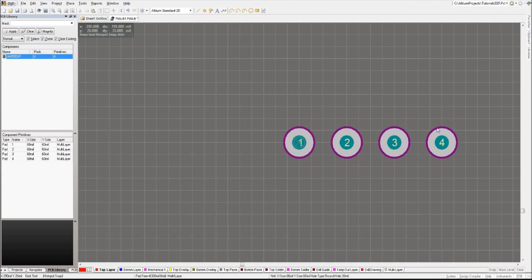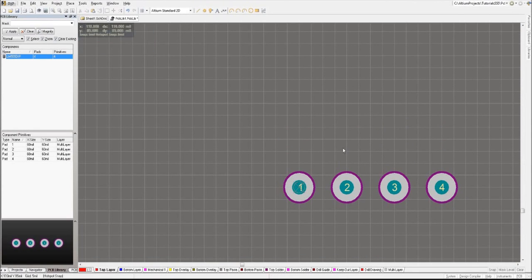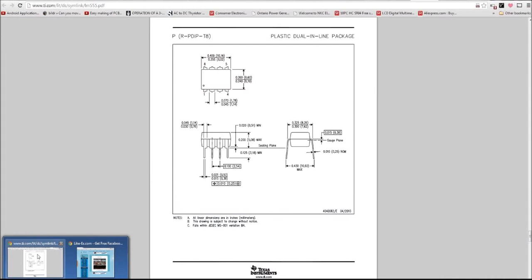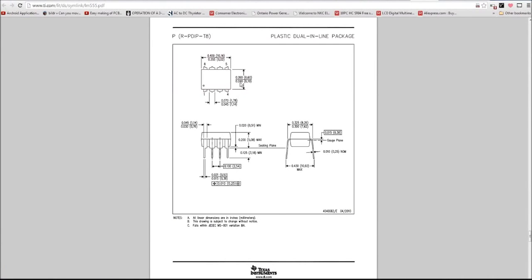So you have your first 4 pins ready for your IC, and now we're going to see what the spacing is between these 4 and the top 4. As you can see, it's 0.24 to 0.26 inches, so we're going to go with 0.25, which is 250 mil. And in this case, you can see you can increment from the 5th pin to the 8th.